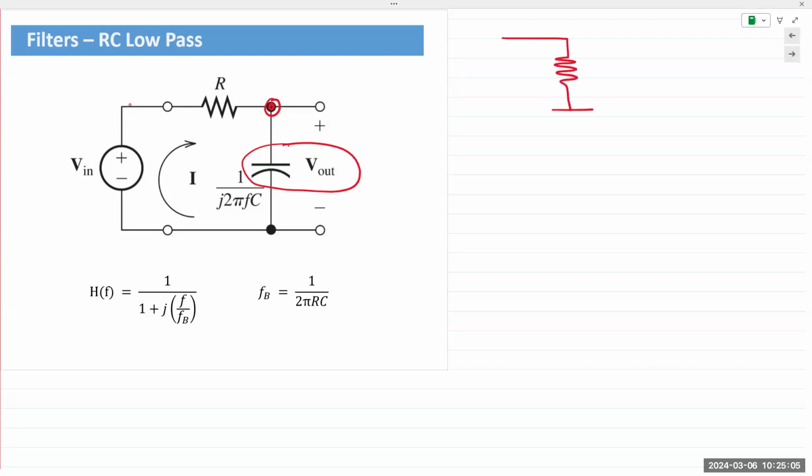And there's a point I'm trying to make with this. The circuit actually looks like that. You're applying a voltage V in, and you take the output across the capacitor. Passive reference configuration applies. Everything still applies exactly the same. When current passes through, the point of entry is plus, point of exit is minus. If you take the output across the capacitor, the positive notation will be at the point of entry, which is at the junction point of the resistor and the capacitor.